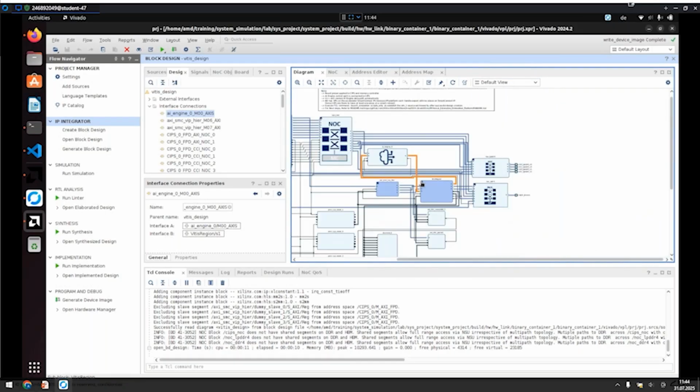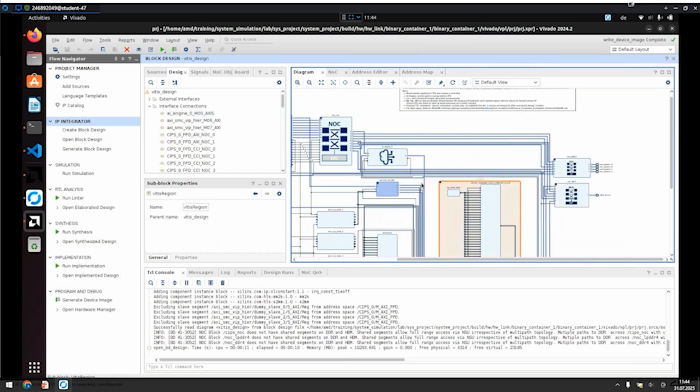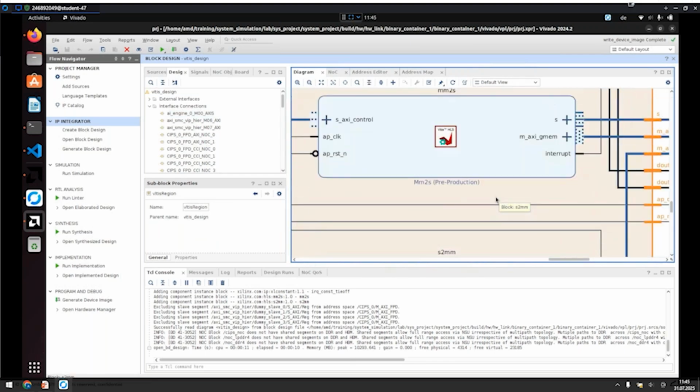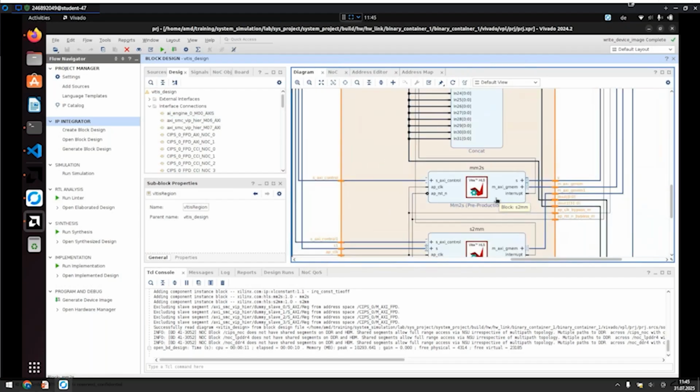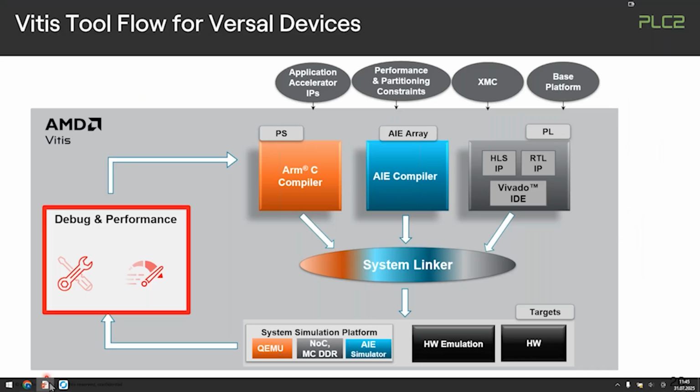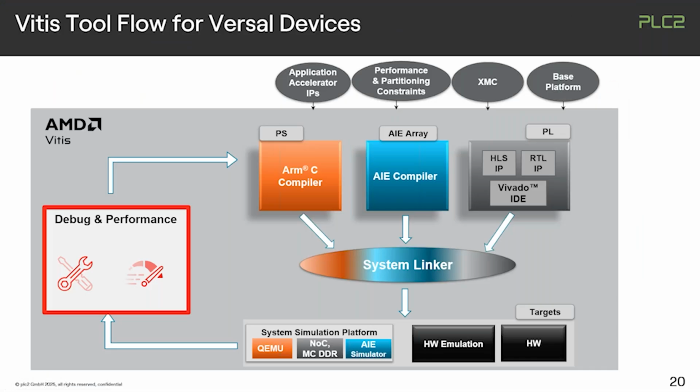The Vitis region block, now you won't be wondering too much, is actually holding our two nice HLS kernels, which got automatically hooked up with the originally empty platform. So that's the way that we need to think about these designs in Vitis. And that would already, in its own right, put you in the position to build something that is completely standing up to get a complete design out of these devices.